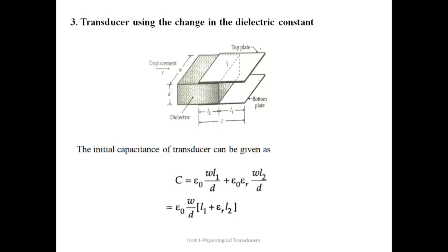Now, up to the height where we want the liquid to rise, when there is no liquid, the dielectric is air, so the capacitance will be something else. As the tank fills up and the level of the liquid reaches that point, the area between the two plates gets filled with the liquid, the dielectric constant changes, and the capacitance changes. So that is a very popular application of the capacitive transducer in level measurement.